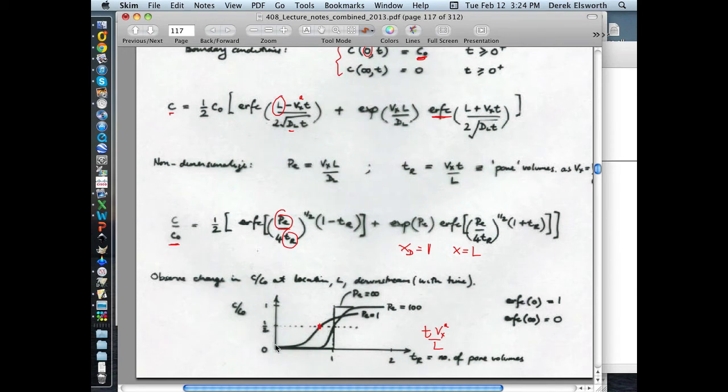So the one that we drew would look like this, right? So this is a Peclet number equal to 1 over 10. So you see the progression of these. And so it was fine to use what we used before to do these calculations for arrival times and also what the distribution would look like. But in this particular case, if you're looking at diffusion-dominated flows, not surprisingly, you can't get the proper arrival times by just assuming that it's an advective flow, because it's not. And so beware of that.